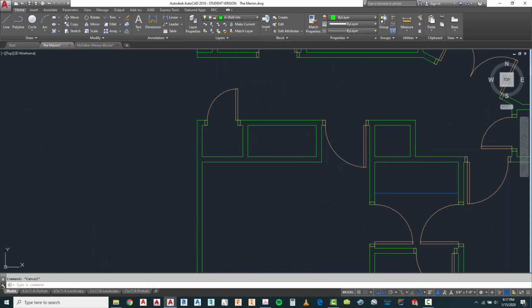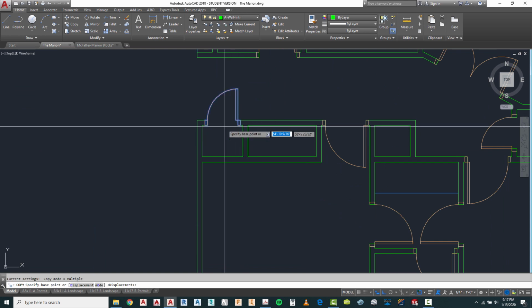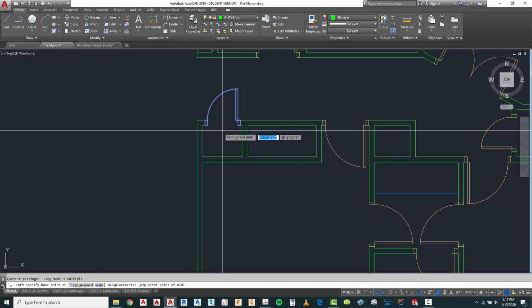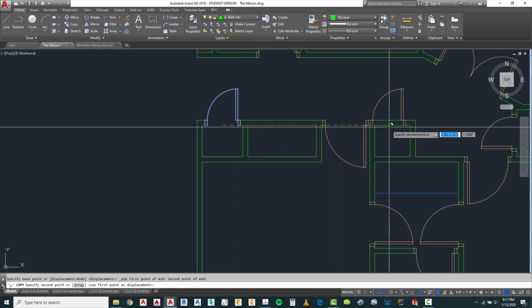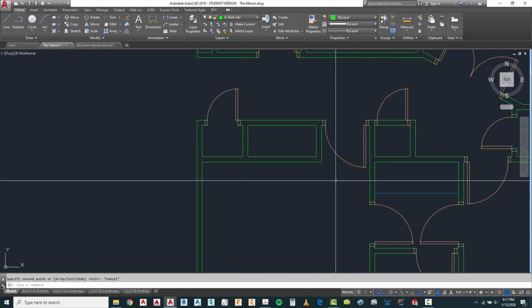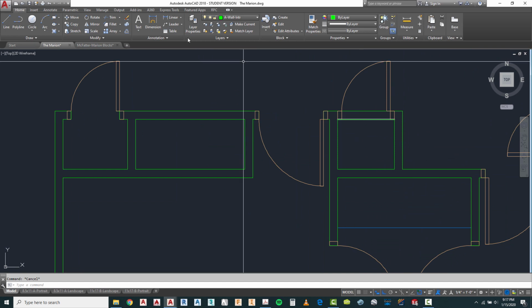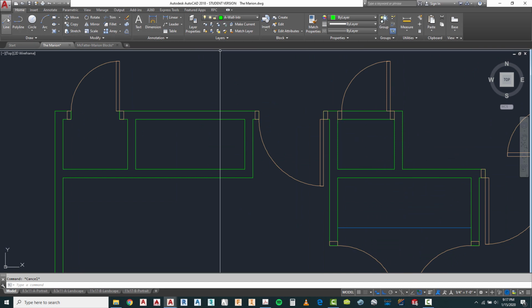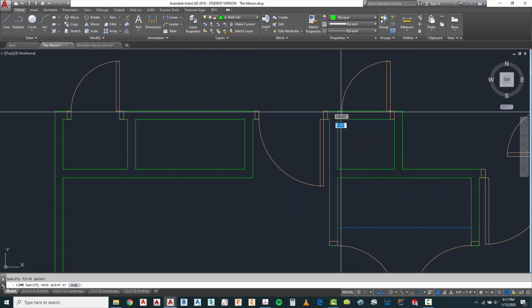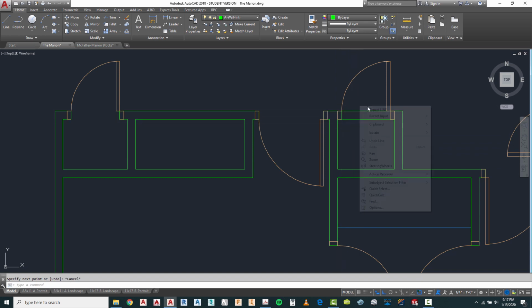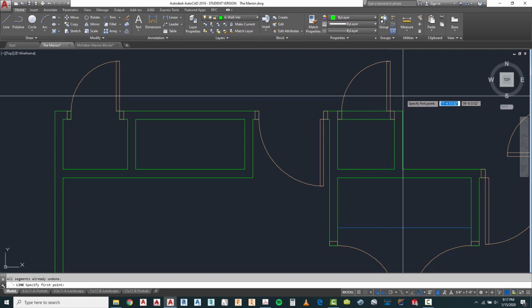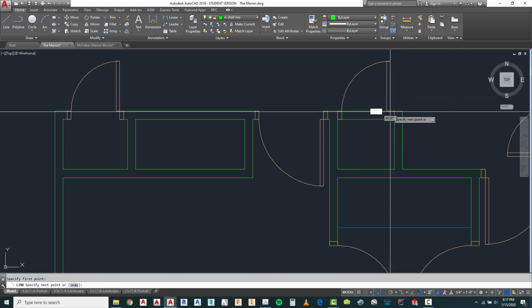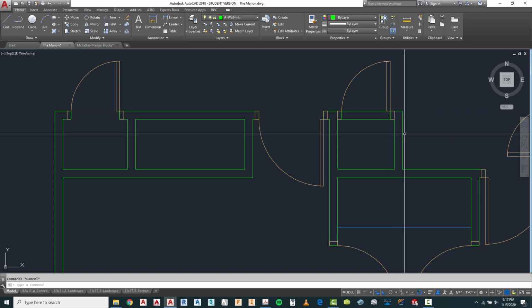We will copy that door, and we're going to use it to specify the base point is the mid between these 2 points. And we're going to bring it right to that point. So let's go ahead and lay out our line work. And here we're still in the A-wall interior. Repeat line. Whoops. Specify the base point here and here. And then I can do the trim command.